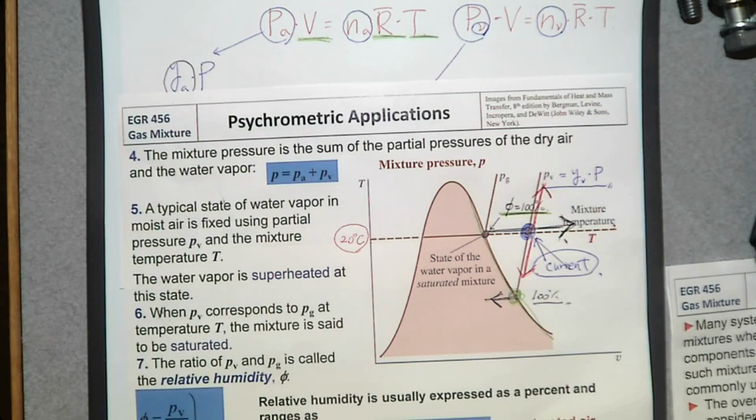So you need to move up by increasing temperature, or to the right by decreasing the amount of water. And can you increase the temperature near the windshield? If you turn the heater on without changing the amount of water, the temperature of the air in the cabin is going to increase. However, the temperature near the windshield is still going to be low because outside is cold.